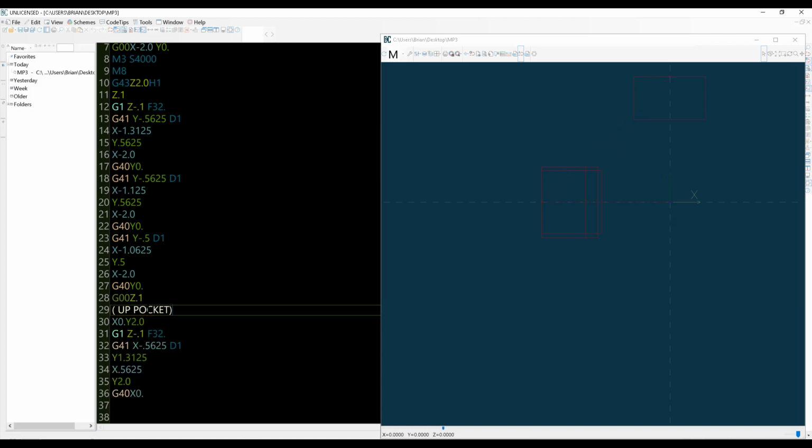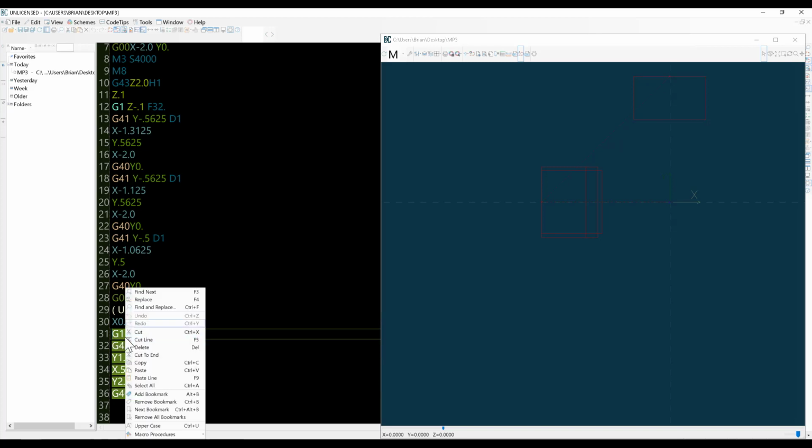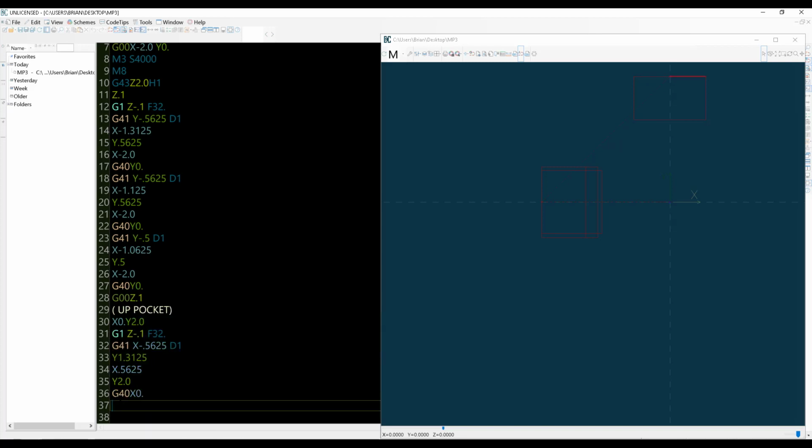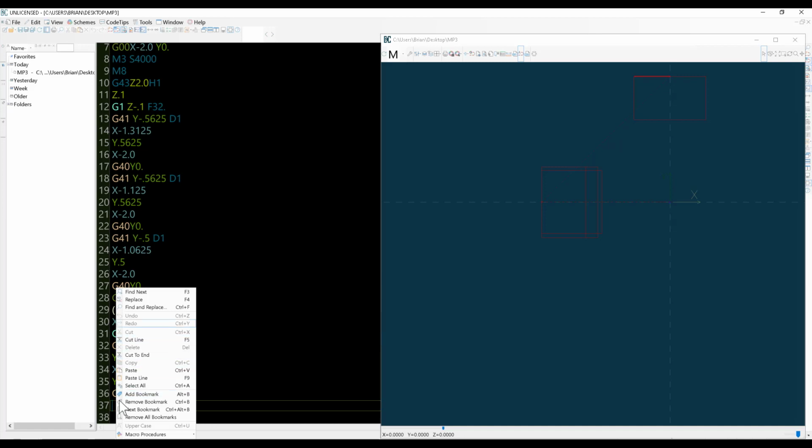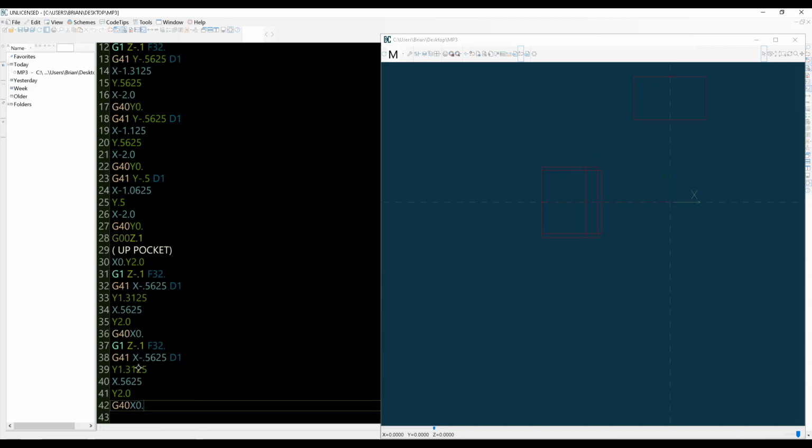Okay, just for reference. And now what I can do is I can copy and paste from here. The one thing is we are going to end up here anyway. So if we did this right, if we copy and paste the lines not including our initial position, this should look right. It should not be any change. Excellent. The only thing we need to change is the Y, our next step, which should be an inch and an eighth, Y1.125. You'll see the cut. We'll paste again,